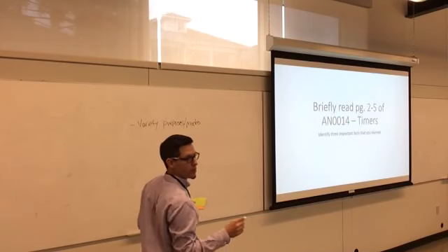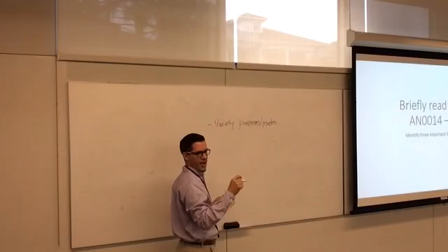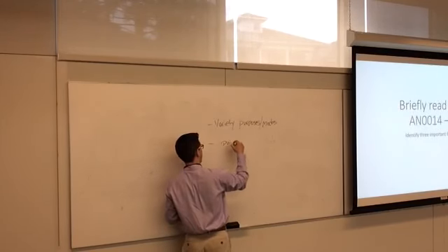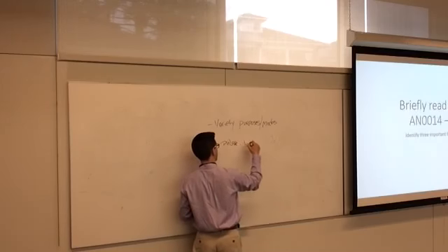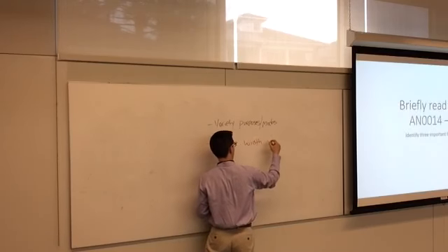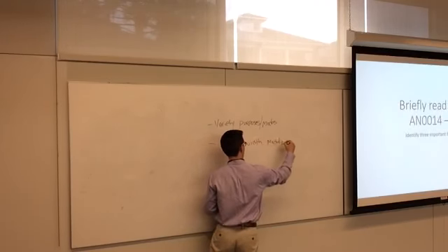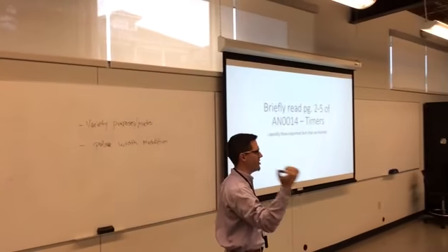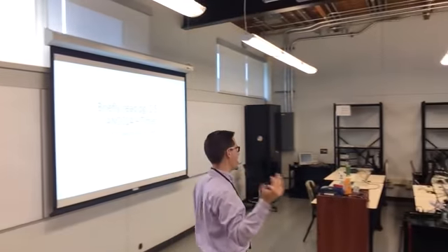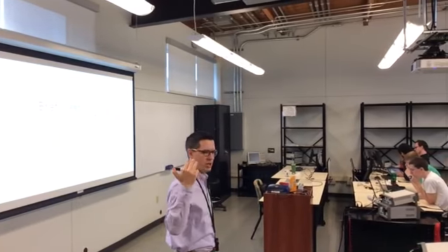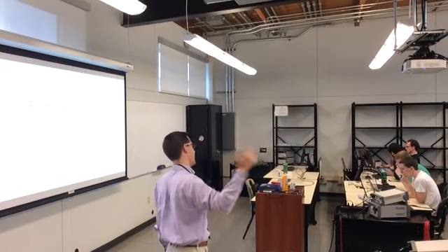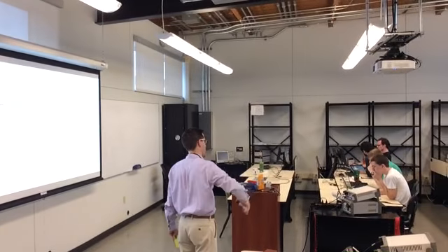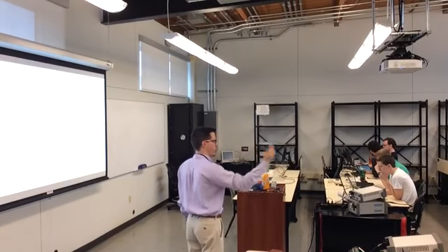Okay, so they can measure it or create it. A very important property of timers is that they can do pulse width modulation. A PWM signal is a square wave with a varying duty cycle, and there are a lot of purposes for that. You can, in general, fake any analog voltage with a PWM signal. So if you want to generate an arbitrary analog wave, you can do that by varying a PWM signal.